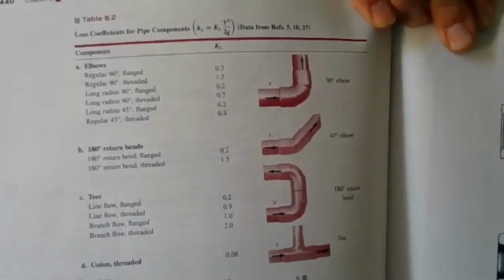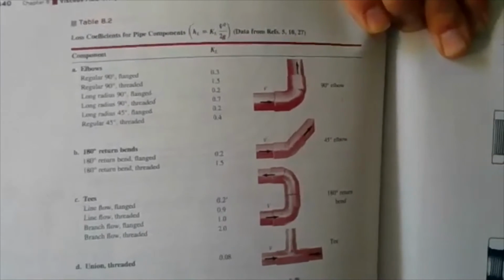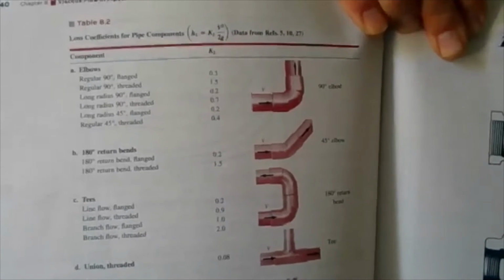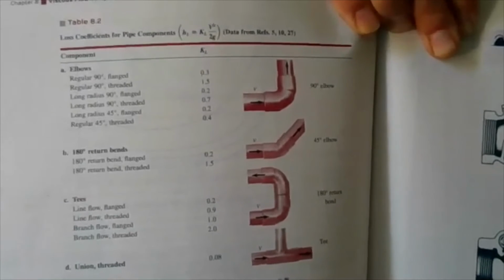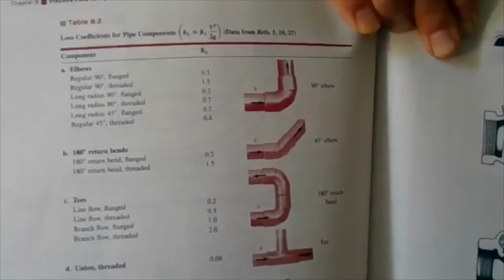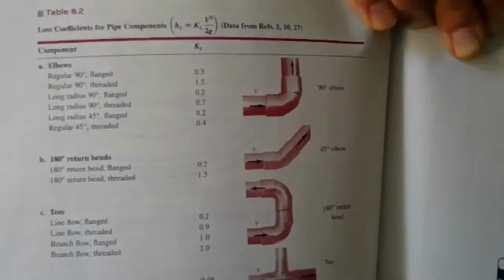Okay, so on page 440 is a table for typical pipe fittings. And I'm just going to start by having you look at the table there for the 90-degree elbows. Basically the idea is you have some sort of fluid approaching an elbow with a speed V, and you want to figure out, hey, what's the loss there in that elbow? Well, you're going to do V squared over 2G, and then you're going to pick the appropriate K value. So taking a look at that, you can see there are various K values. I'd like you to look at the threaded one. That K value is large, which means that the loss is going to be large.